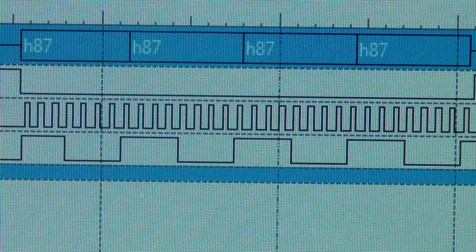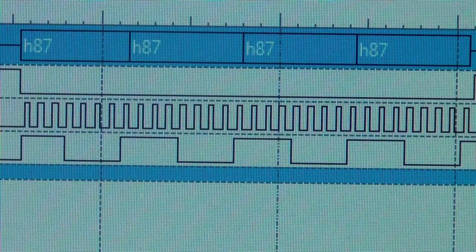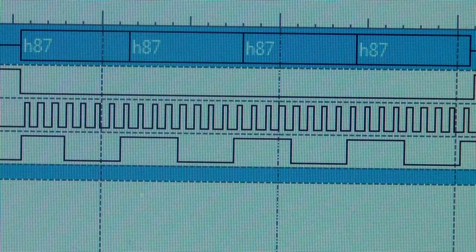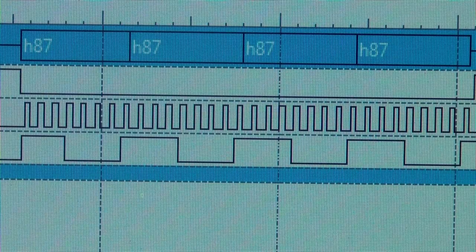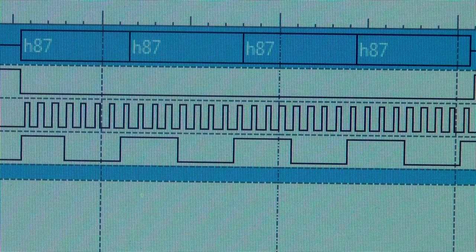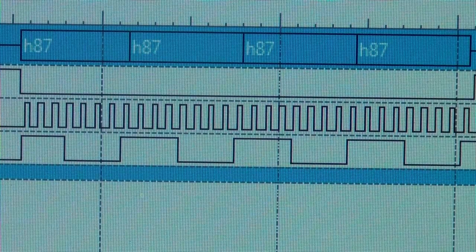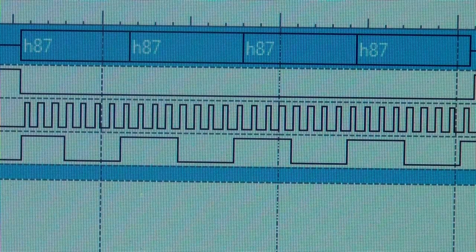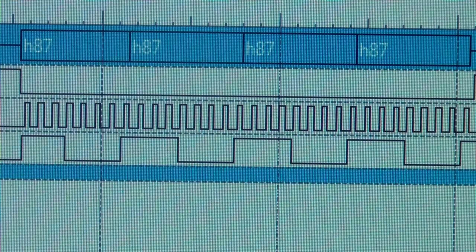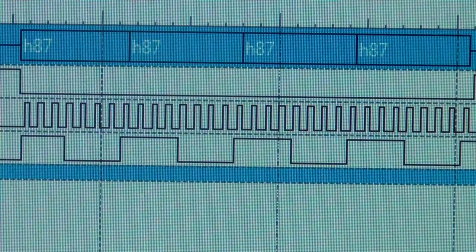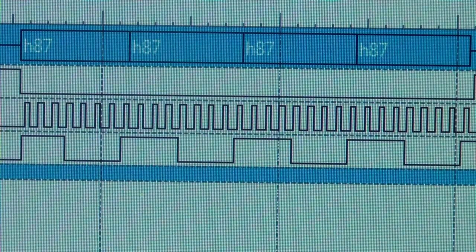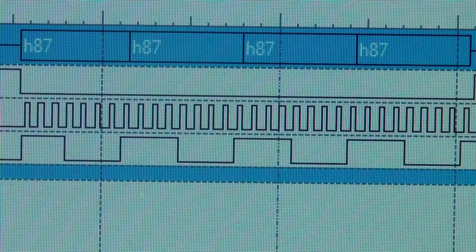And that's one of the reasons that I think the Analog Discovery is really the optimum. It's very inexpensive, so you can afford several of them, many stations. It's nowhere near as fast as a good oscilloscope. It's only 10 megahertz, but it really is, in my opinion, the best approach for a university lab environment when it comes to bus decodes.